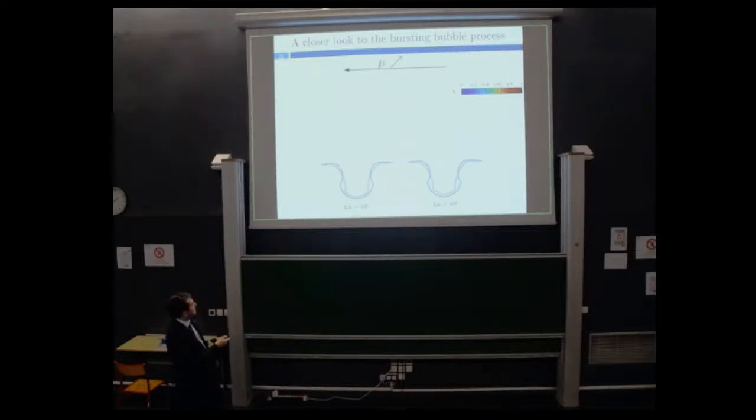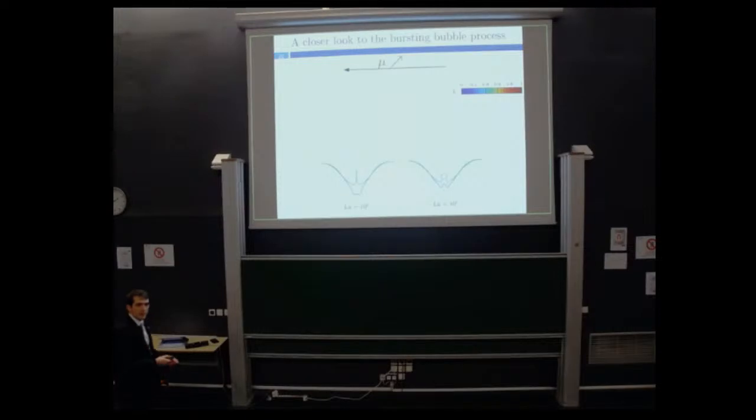And if we observe the jet formation, here at a Laplace of 100,000, we can observe the formation of a jet. This jet is very thick and very slow. And if we compare that with a Laplace number of 1000, we've got a very fast and very thin jet. So that explains why we are producing the fastest droplets at a low Laplace number. So that explains why increasing the viscosity increases the ejection velocity of the first drop. And now we can, of course, observe the rest of the simulation and the production of all the droplets.